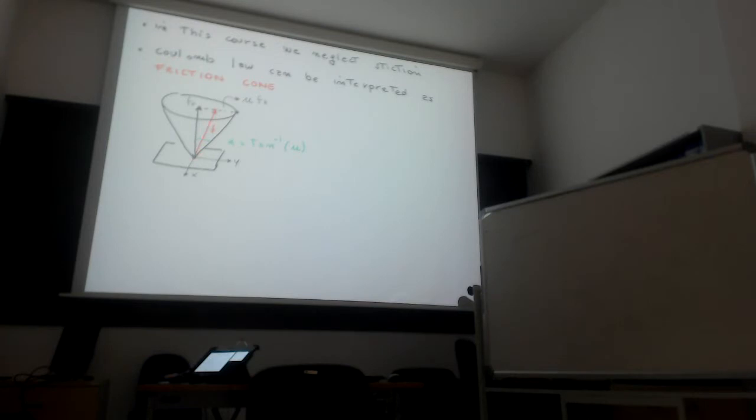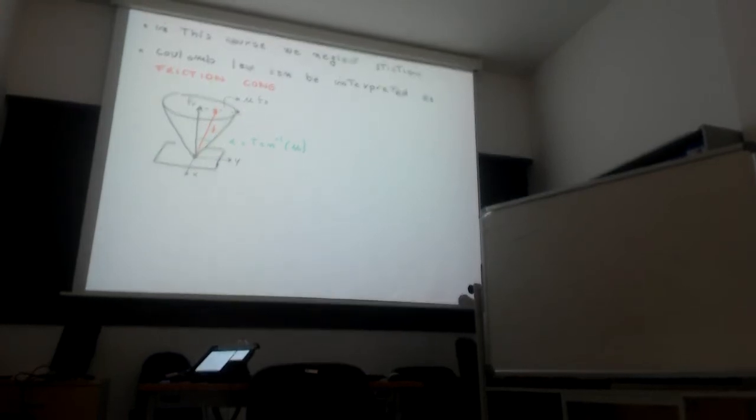And we see that defining the friction force, the tangential force, as related to the normal component is like saying that the friction force should stay inside a cone, where the base of the cone is the maximum allowable value of the tangential force, proportional to the Fz component.